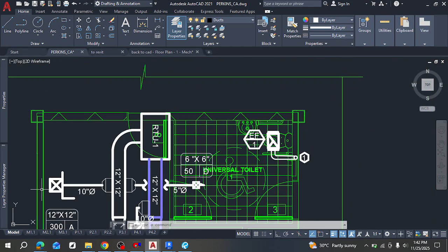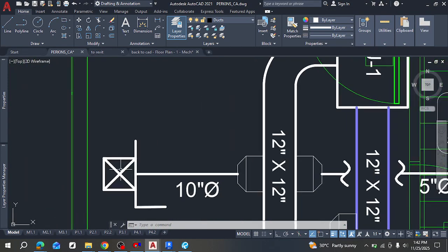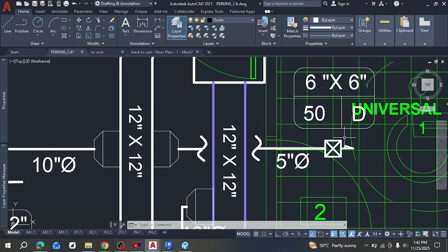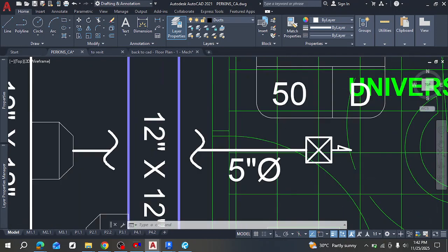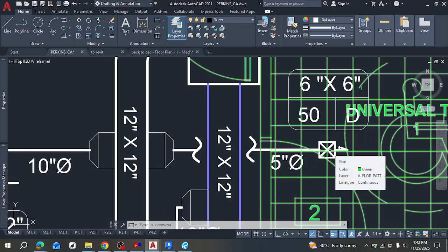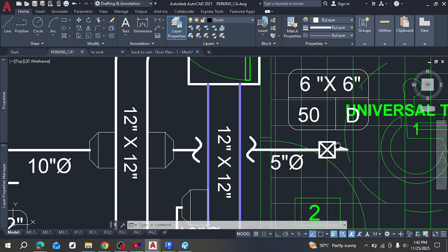For these other ducts, air might be able to seep past it. So here you're specifying that for this register, it should be like a one-way valve, and that means air can only go in and not out. That is another reason why this arrow is here. So the type of register to put here is a one-way type. That's what directional means.